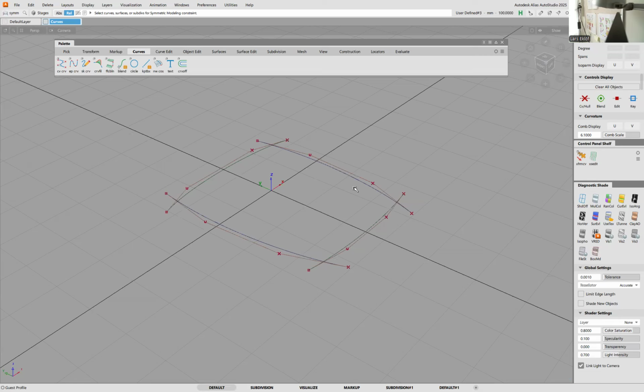I can then round off the corners, for instance, here and here and here and here and so on, using the fillet tool, surface fillet tool, or even a round tool would work if I trim those surfaces. But I make them oversized to begin with to capture the basic shape that I want.